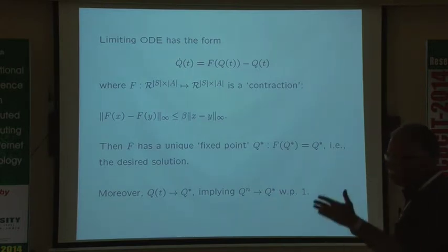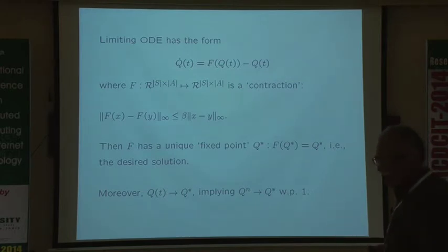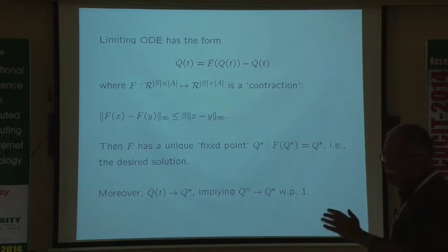So it tries to strike a balance between the two. For example, if you have a randomly varying channel and you are doing what's called opportunistic transmission, when the channel is good, you want to push as much as you can because it takes less power. When the channel is bad, you don't want to transmit, but then you are queuing up, so there are delays. So the cost which I just mentioned captures this delay and power trade-off. So that's one example.